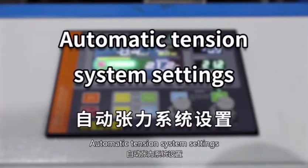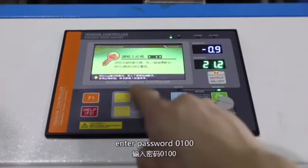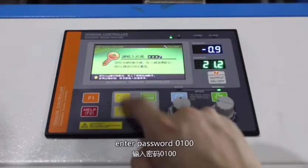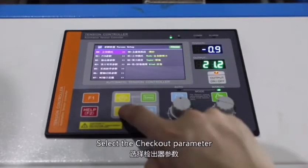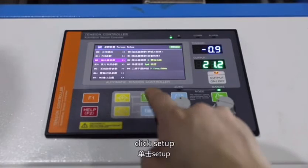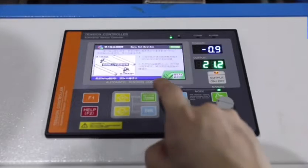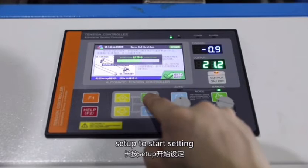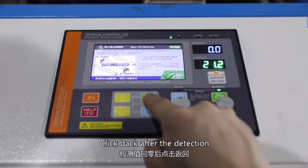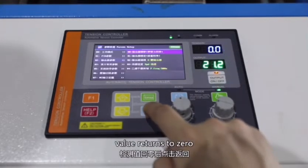Automatic tension system setting. Click Setup. Enter password 0100. Select the checkout parameter. Click Setup. Select the checkout to adjust 0. Enter the 0 interface and press Setup to start setting. Click back after the detection value returns to 0.